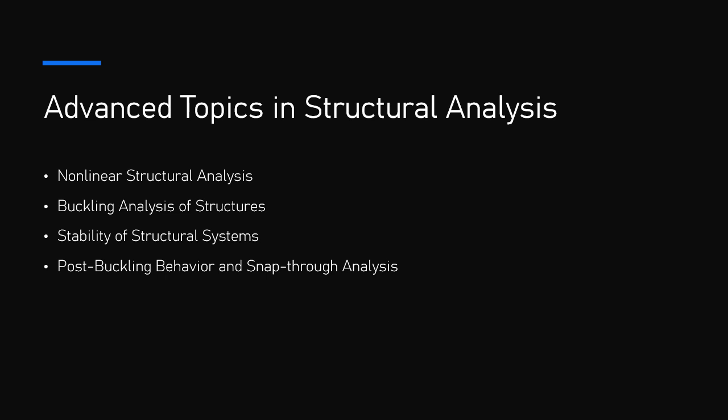3. Monitoring and maintenance. Structural health monitoring, SHM, is crucial in maintaining the stability of aging structures. Systems that measure displacements, strain, and temperature changes can help detect early signs of instability or failure. Regular maintenance and inspection are necessary to identify any degradation in structural elements, such as corrosion or fatigue, which may reduce stability over time.